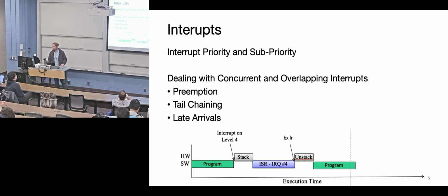All right. So when the priority is high enough, like if an interrupt came with a late arrival behavior and had more priority, that would be executed first. Right. So let me say that. We've got mythical interrupt 5, which is not shown here, where my finger is, that comes in and it is less important, then it goes to pending. If it's more important, then it gets executed first.